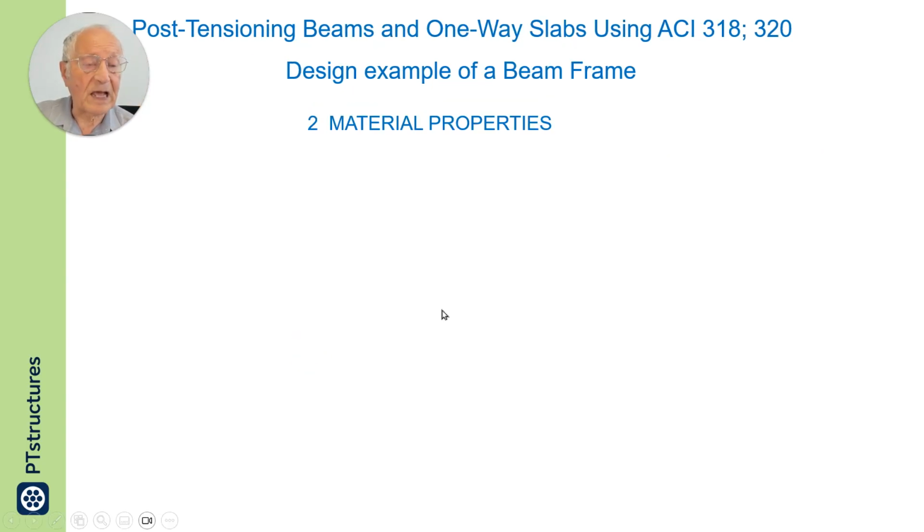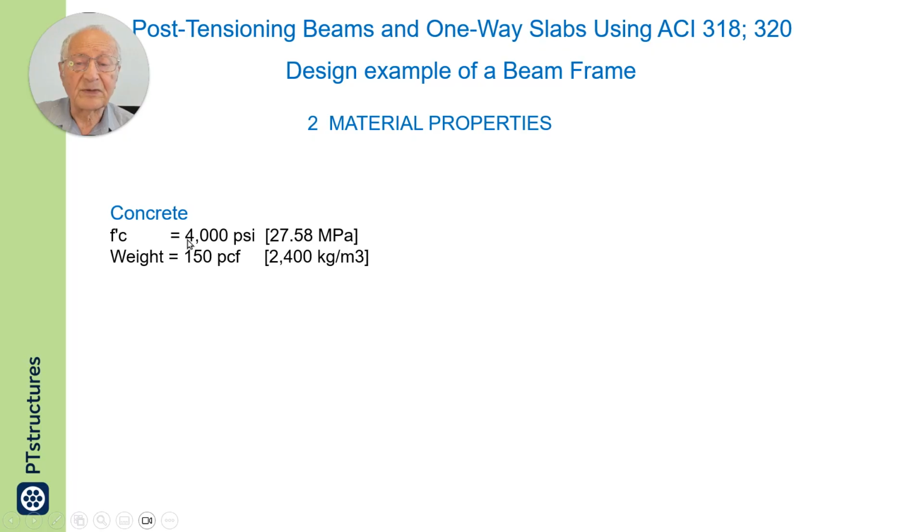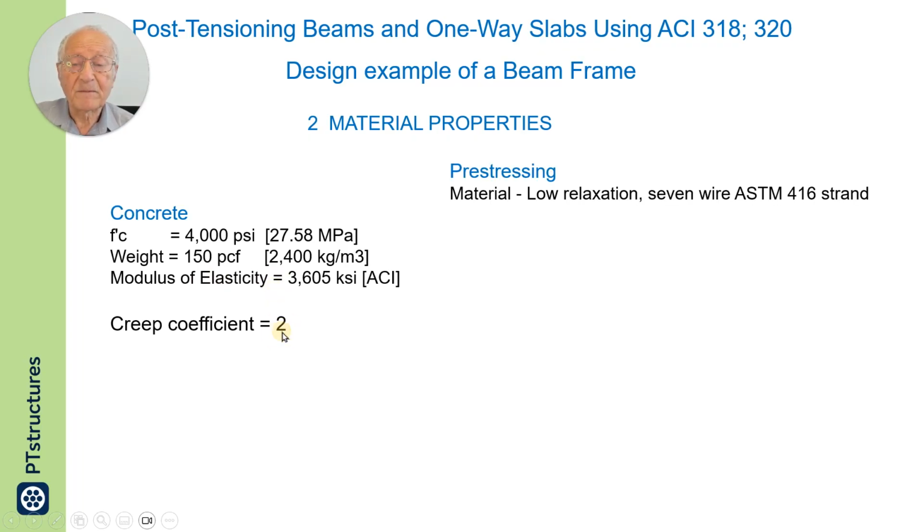Then after geometry, we go to material properties. For concrete, this is what I have assumed. For strength and weight, modulus of elasticity, creep coefficient of 2.